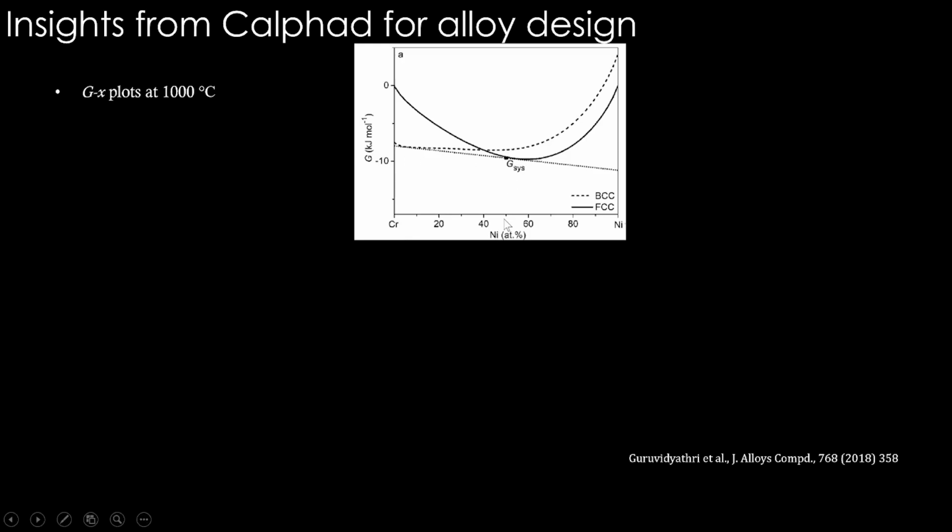Let's say here at 50-50, if we add chromium nickel to an alloy in equiatomic ratio, we can look at this diagram at 50-50 and see what is the Gibbs energy here. If this value of energy here itself is low, and it shows FCC, there is a strong tendency for favoring FCC. So that is one quantity we can use.